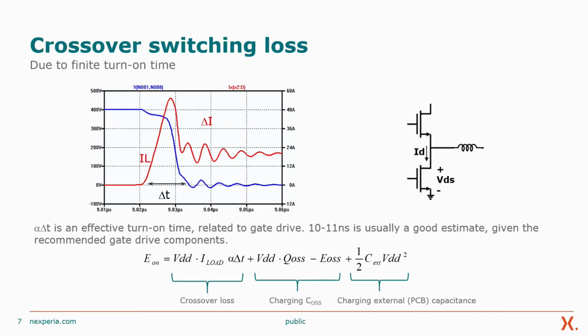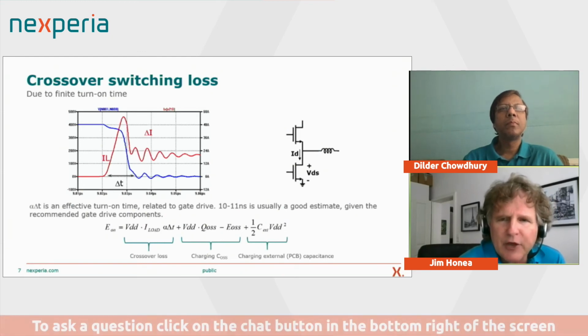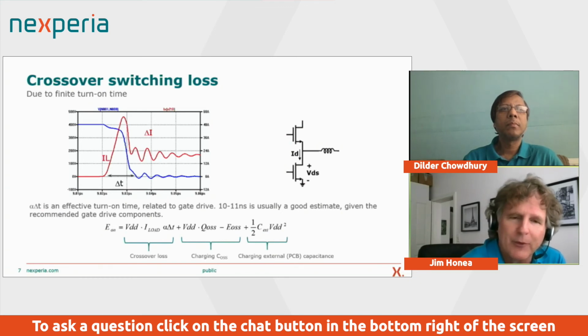But it's like any kind of energy capture, soft switching approach, active clamp kind of thing, where you have to be very careful that it is helping at every stage of the switching process, right? Because what you're really saying is you're going to put energy into that parasitic inductance. When will it come back and in what way? So if you can be clever about making sure that it doesn't come back and hurt you at a later stage, then yeah, absolutely. You can use a parasitic inductance to lower the drain source voltage at the moment of switching.